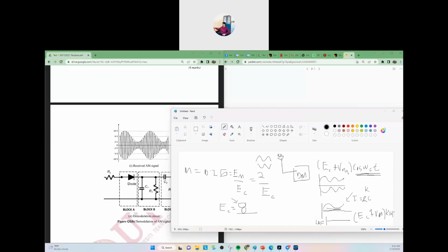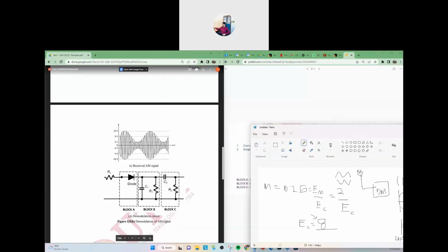So pretty much, if you see, this is actually a DC component and only the lower frequency signal, which is our modulating signal. Carrier is already filtered out. Because it is a modulating signal with DC, it is actually shifted up by a DC value. Depends on what this is, it will be shifted up, and after that you will have the signal pass through